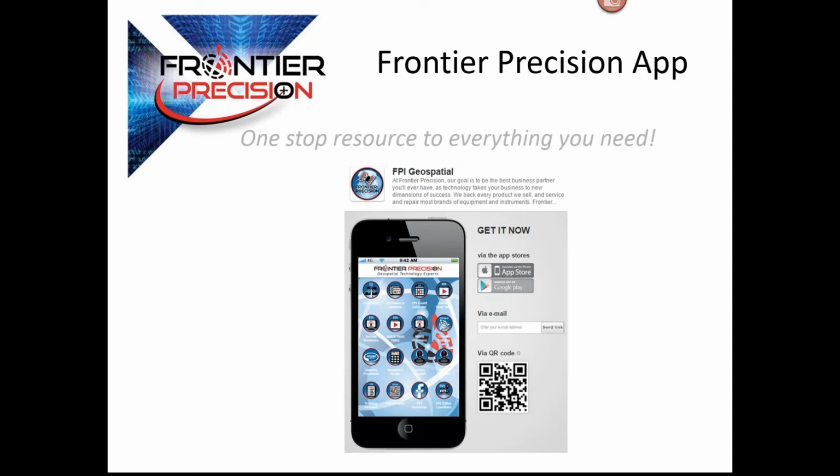So a vertical calibration may be necessary. Once you calibrate vertically, just like you would with a single base, then your precision should be just the same as if you were setting up a single base, with part per million error relative to where you did your calibration. If you use multiple points of vertical for the calibration, you're going to get a better result.